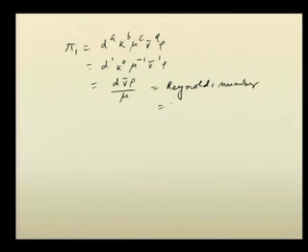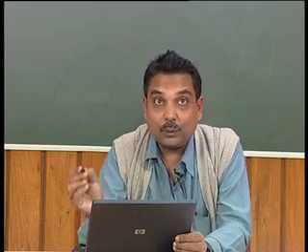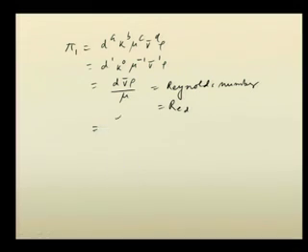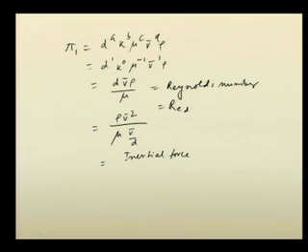And we express it as Re based on diameter. So, d is the diameter, that is the characteristic length. So, this is Re based on diameter, and we also know the physical significance of the Reynolds number. We can write this as rho v bar square by mu into v bar by d. Okay? So, rho v bar square is called inertial force, and mu v bar by d is called viscous force.